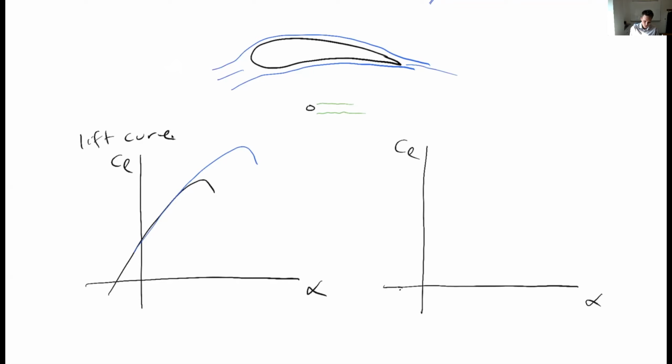So I guess this is what is called CL max, right? That's one thing I want to look at. What's my CL max in general? A higher CL max is going to be better. But I've also got to think about other things. Maybe I've got an airfoil that has a very gradual stall before another one. Let's say that maybe it's a higher CL max, but it's got a very abrupt stall.